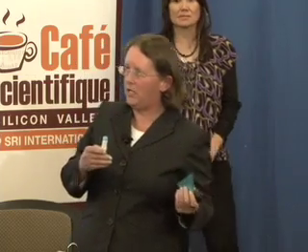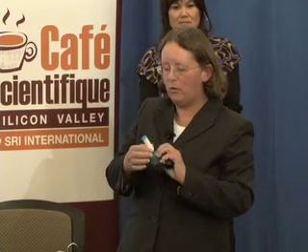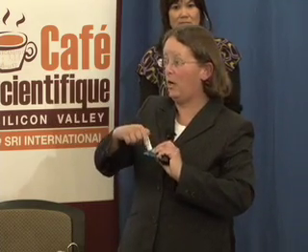And so when the laboratory gets this, they will desorb, or in some cases chemically extract, the contaminants that are on that carbon sorbent, and then they'll measure what's there and then use the Q value to figure out what the equivalent air concentration is. So the research study that Alana and I and a couple of other coworkers worked on was to really see if these were as good as the SUMA canisters. And we pretty much found that they were. So we're seeing this as a potential new technology that we might see more use of in vapor intrusion studies.